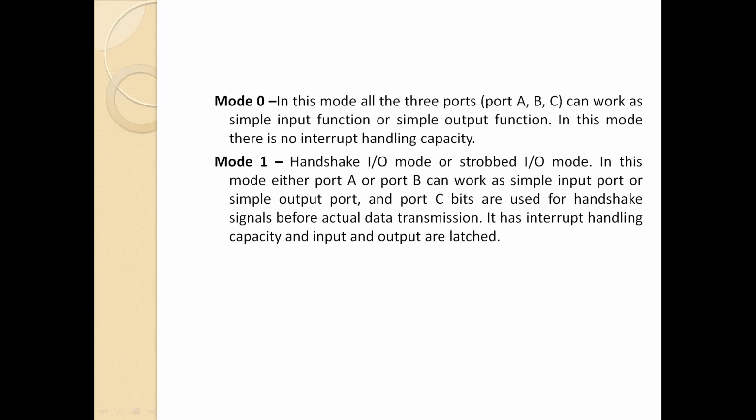Now, we talked about mode 0, mode 1, and mode 2 in the input-output mode. So what happens in mode 0? In this mode, all three ports, port A, B, C, can work as simple input function or simple output function. Here, there is no interrupt handling capacity.